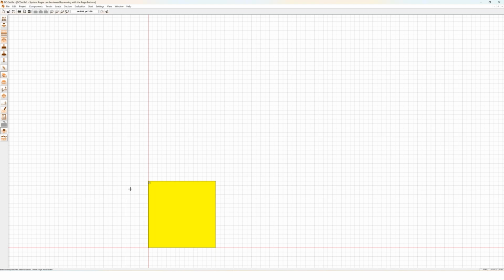Then we can also define a section line with this function here. We draw a section line and end with the right mouse key, say OK. With this section line, you can see the layer thickness, the foundation and the settlement line, as we'll see in the output later.